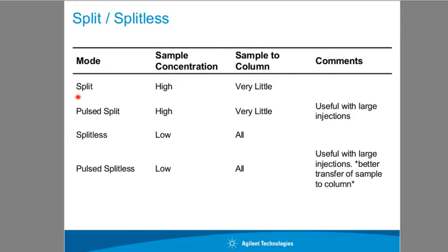Many of you know that you have split mode and you have splitless mode, but you may not know that you also have a pulsed split and a pulsed splitless option with that too. And again, going through the next set of slides here, we'll get into why this can actually be beneficial for your application.